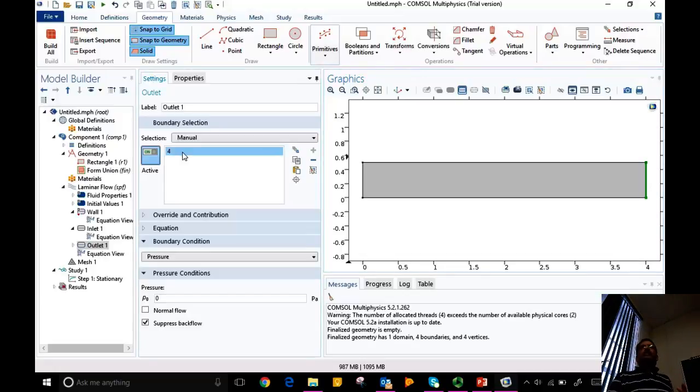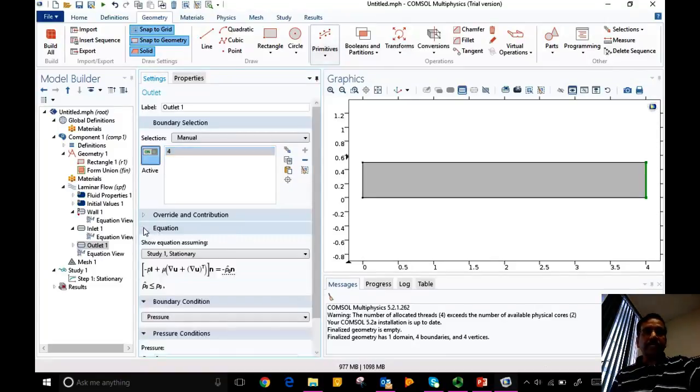But what is the outlet boundary condition? In Fluent, you won't get a clue because you just check a box, just like you do here. But here it tells you what equation is imposed on the outlet boundary. The exit pressure is 0. If you check that equation, it expands. This is the equation that is imposed at the outlet. What does that equation tell you?